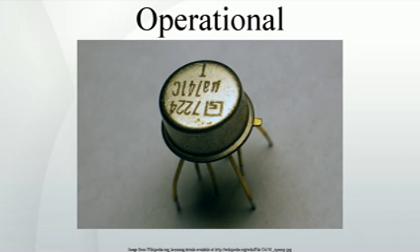Non-inverting amplifier. In a non-inverting amplifier, the output voltage changes in the same direction as the input voltage. The gain equation for the op-amp is given. However, in this circuit V is a function of Vout because of the negative feedback through the R1 R2 network. R1 and R2 form a voltage divider, and as V is a high impedance input, it does not load it appreciably. Consequently, substituting this into the gain equation and solving for the gain, if A is very large, this simplifies.